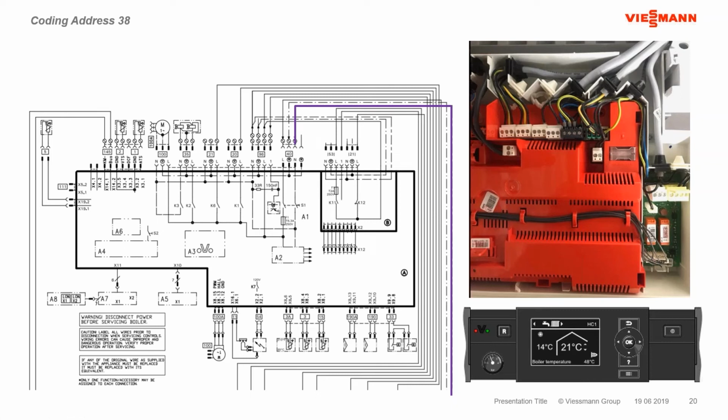So carrying back with that neutral that's purple, the first thing that's going to hit when it comes up from the pump module is another 40 plug. So a green 40 plug that sits in your control console, and then once we plug that 40 plug in, it sits at S1. So S1 is your power switch.